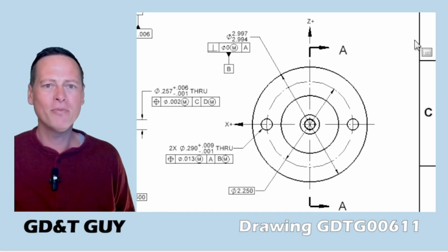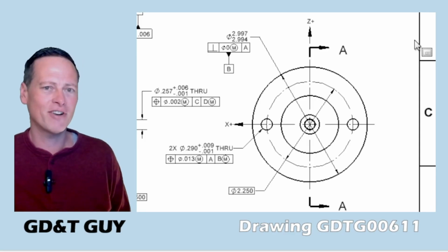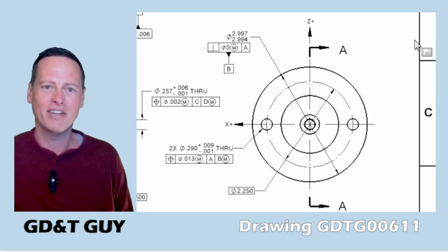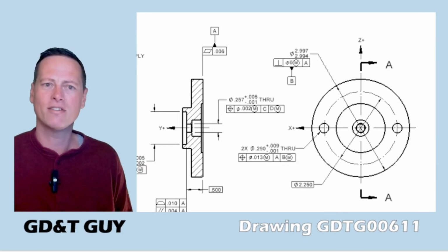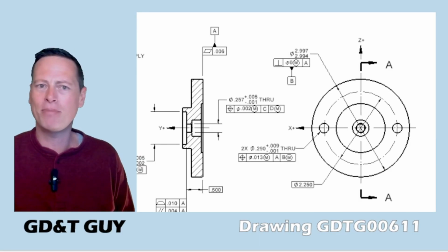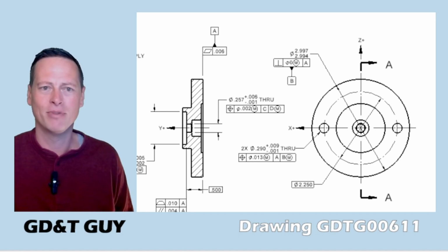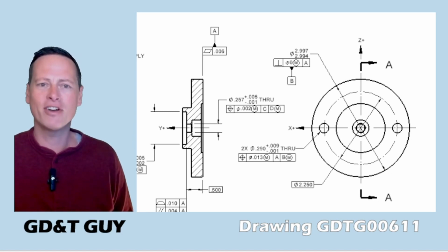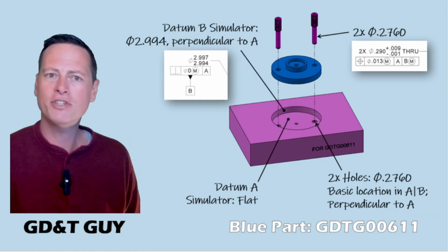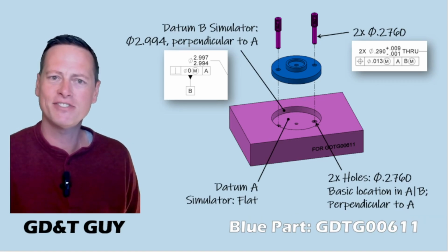If that were possible, it would explode the fundamental concepts of position tolerance. This horizontal center line that goes across the part, it means something. You can't just ignore this. So these holes are related not only to datum reference frame A primary, B secondary, but they are located as a pattern of features to that datum reference frame, and therefore to each other as well. And so to pass or fail manufactured parts, you could have a gauge like this.